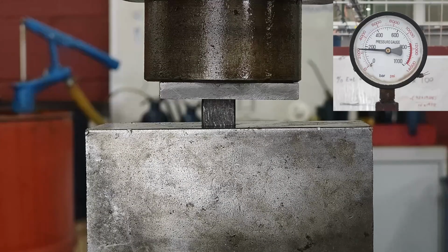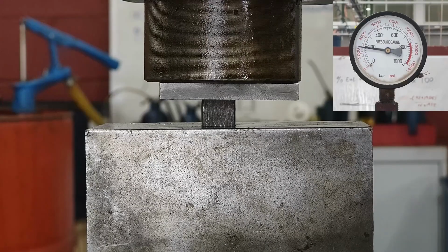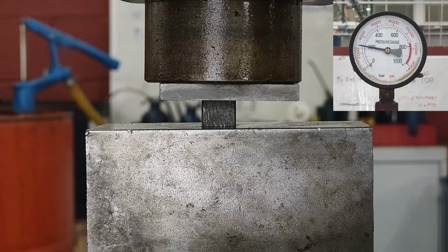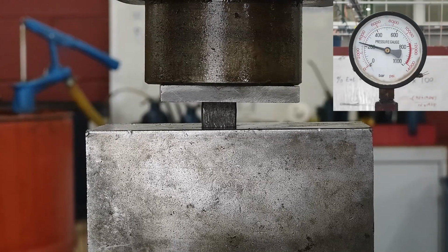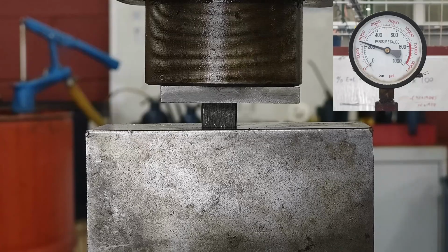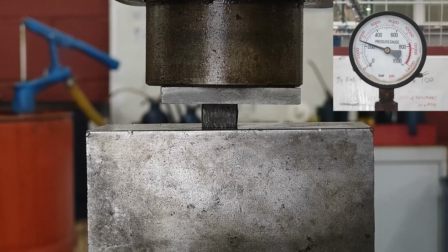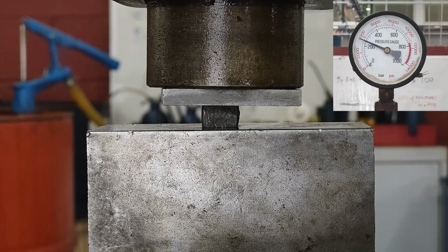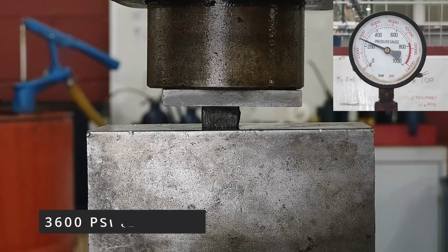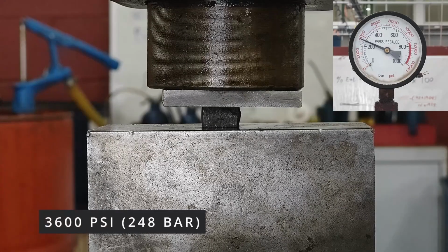Grey cast iron can withstand a significant compressive load, as seen. When the test sample starts to fail, fractures start to appear at 45 degrees to the normal plane and propagate throughout the material. This fracture is a brittle type fracture. Cast iron performs well under compression, but poorly under tensile loads due to the structure of the material.